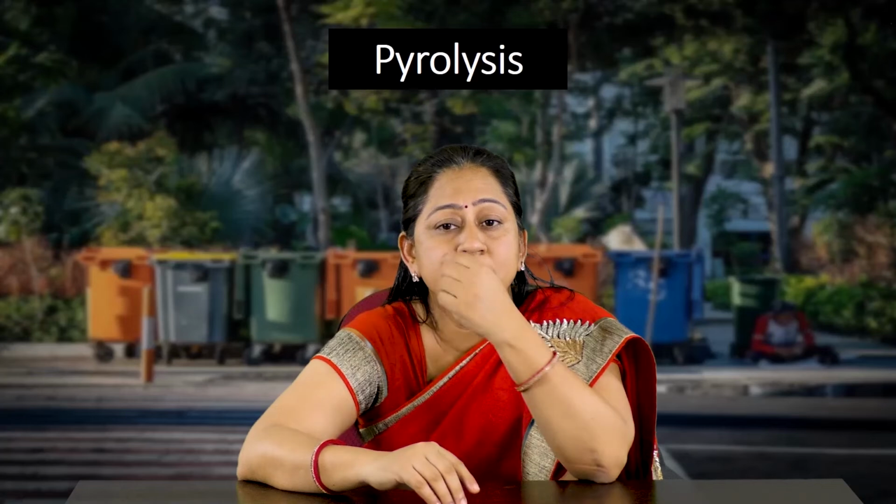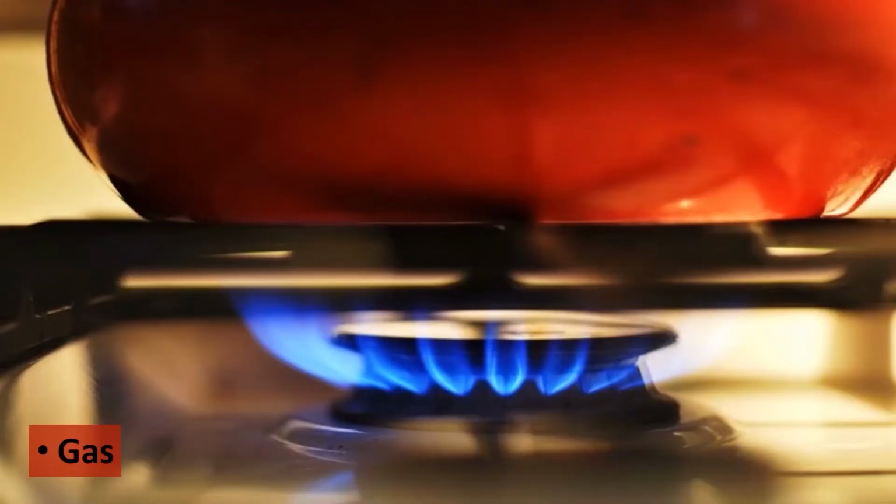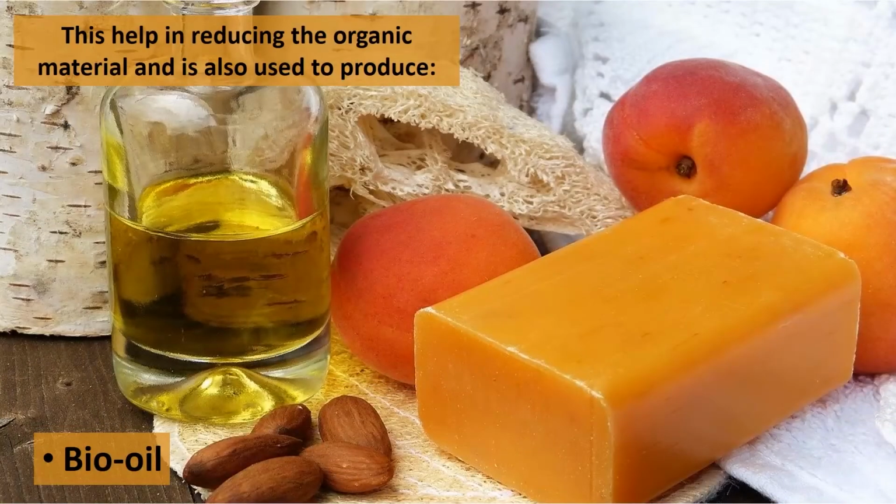Then pyrolysis. Pyrolysis involves decomposing organic matter at a very high temperature, from 400 to 1000 degrees Celsius, in the absence of oxygen and at very high pressure. It leads to the generation of carbon ashes. With the help of this, biogas and bio-oil can be made into some use, but the only condition is that it should be properly segregated, because if the waste is heterogeneous, then the efficiency of the gas and the oil you are producing by this method will be of not much use.